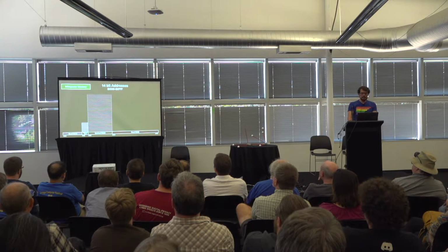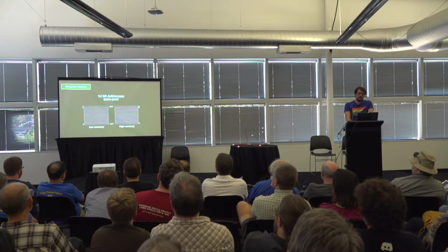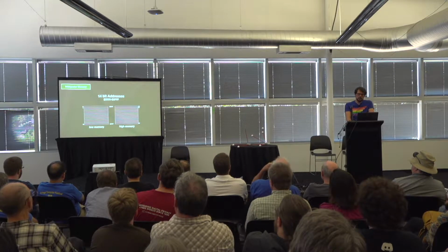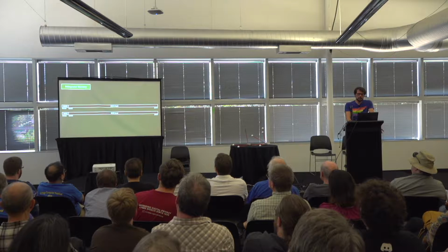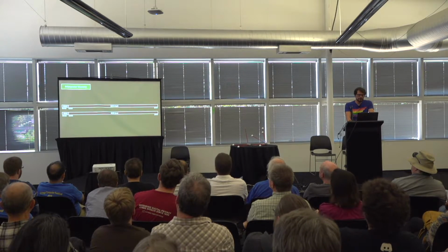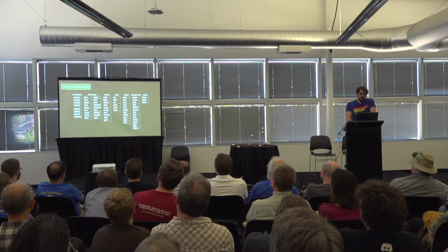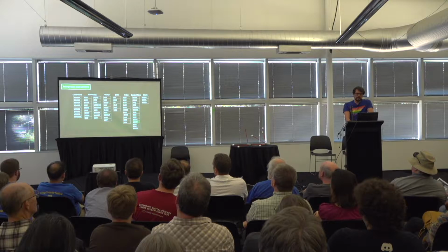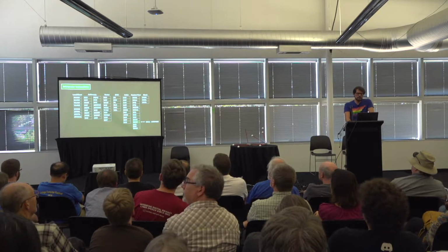14-bit addresses means interpretive code doesn't have to work with this complicated memory layout anymore. It allows addressing about half of the ROM at the same time. At the lowest kiloword of each half, RAM is visible. So interpretive code can pick between one of these 2 layouts. This is the complete instruction set of the interpreter. Regular machine code and interpretive code can be mixed and matched inside of a job. The exit instruction will continue executing regular machine code at the next address, and call interpret will similarly switch to interpreter mode.